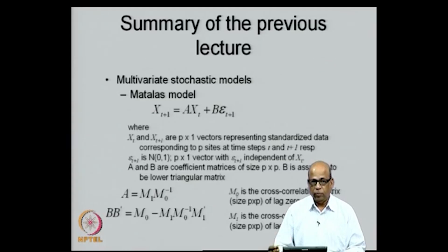And this we distinguished from the single site models, which essentially preserve the statistics of flows at that particular site alone in terms of the mean, the variance and the lag one correlation and so on. In the multi-site models, along with preserving the means and the standard deviations and lag one correlations at that particular site, they also preserve the cross correlations with other sites in the same basin.